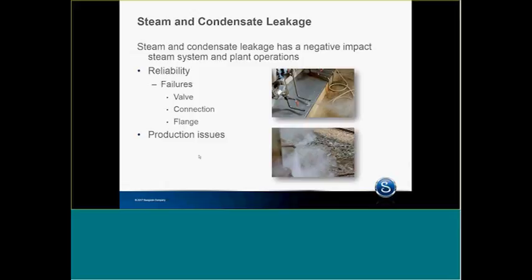The other thing is that we have failures out of flanges. We've got to shut down parts or segments of the plant to correct the leakage. The thing with that is, again, now I've got to schedule a shutdown of that plant to correct this leak area.